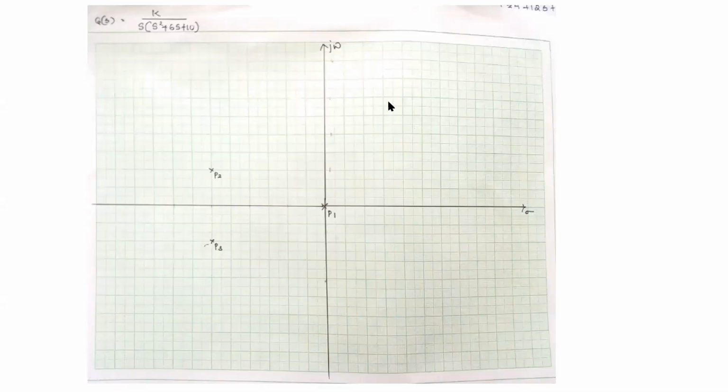Suppose I consider a test point here, what will happen to the right hand side here? The poles and zeros count is odd. So from this end to this end, this is how much? Minus 3 to 0. So this is a part of root locus. Anything on this side? If I consider a test point somewhere here, we have 3, an odd number. So the entire negative real axis becomes a part of root locus.